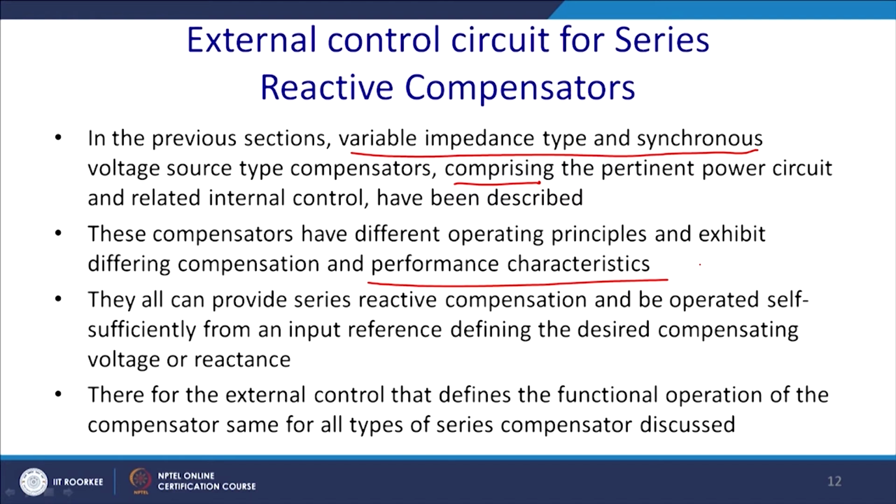So, while discussing these FACTS devices, we have discussed a few control techniques of the voltage source inverter. You can see that space vector is best fit to this solution. So, we shall try to fit the space vector modulation technique for basically SSSC.